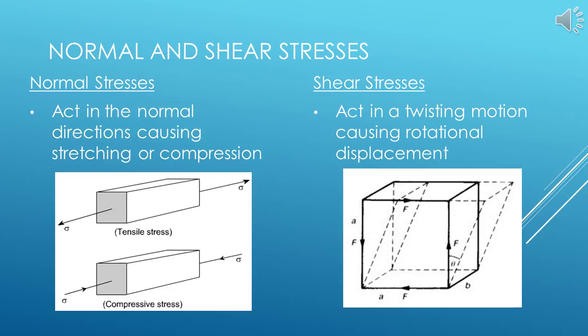But first, a little understanding of the different stresses is important. Normal stresses are either compressive or tensile and can be best visualized if compared to a slinky. If you pull on a slinky, a normal stress is applied and it stretches. When you let go, this stress goes away and it returns back to its normal state. Shear stresses are square or rectangular shapes that deform into parallelograms. This is like if you push an eraser back and forth and it stretches in either direction.